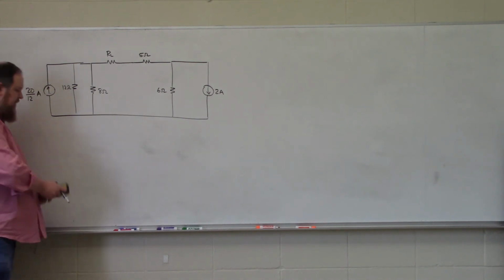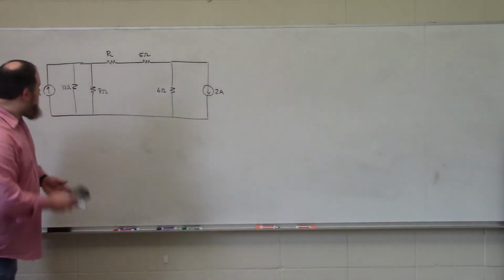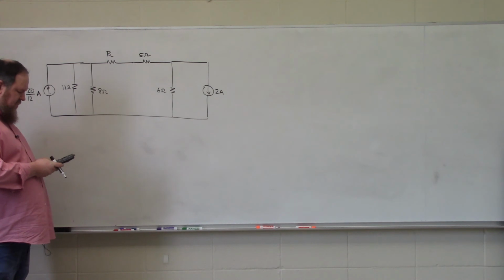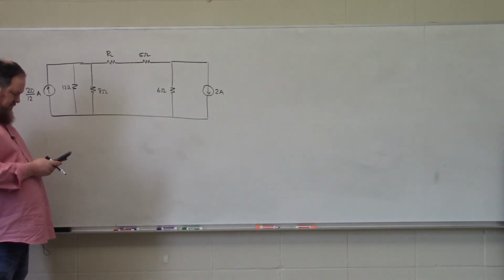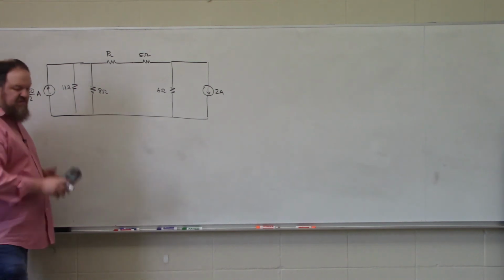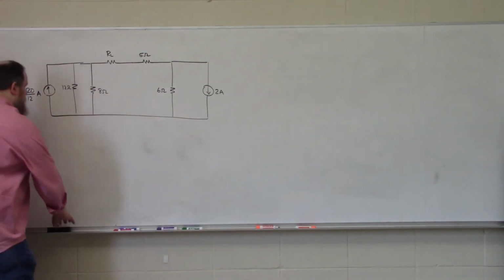So that would be 12 times 8 over 12 plus 8, which is a 4.8 ohm resistor.